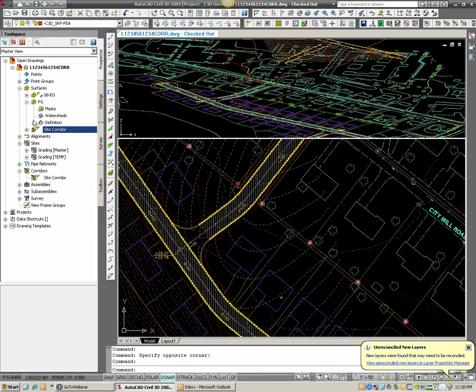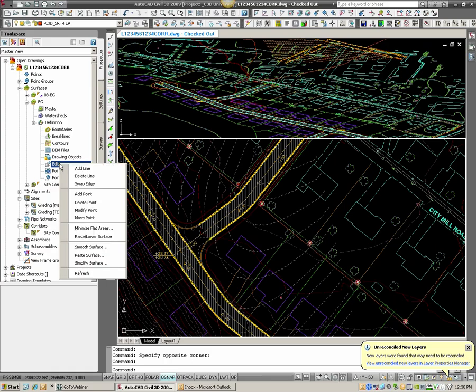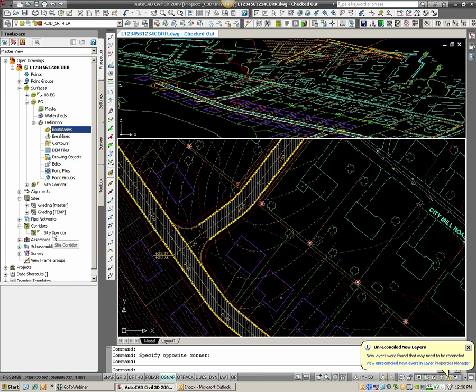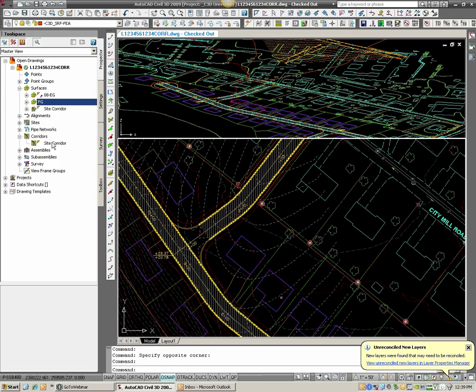And what I want to show here next is called a surface paste. I have this FG surface created, but there's nothing in it. Let me turn off my phone here, sorry. I want to paste in my corridor surface, so I'm sort of creating this linked chain. The site generates this surface. This surface I'm now going to paste into my FG surface.